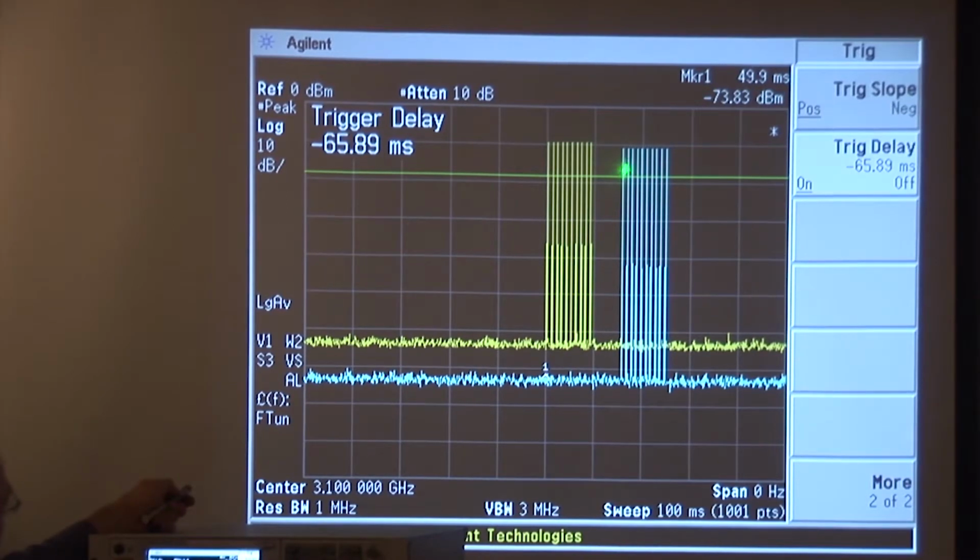Here we're measuring virtually minus 10, and that little bit of amplitude offset between the 1 megahertz measurement and the 8 megahertz measurement, which is yellow, is nothing more than the slightly different amount of power that we're getting in that fundamental lobe when we're in that 1 megahertz bandwidth. Now I'm going to go to a narrower bandwidth. I'm going to go down to 100 kilohertz.